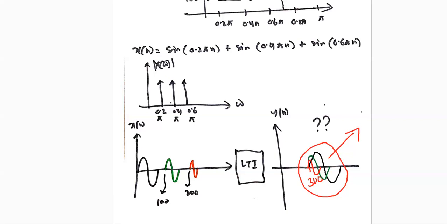By introducing the IIR system, you can introduce the pole location rather than situating it in the origin. So you can shift the pole location, and by changing the pole location, you can improve the quality of the filter very easily. In case of FIR system, you need to introduce more order to improve the system.